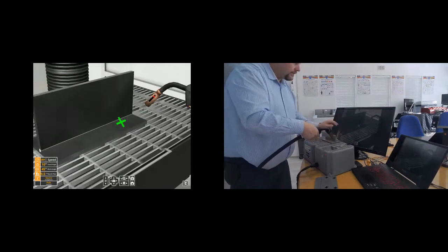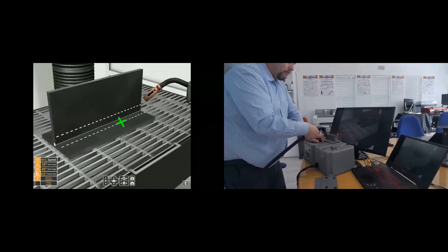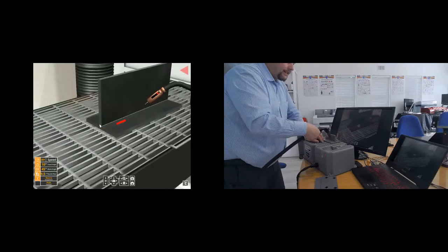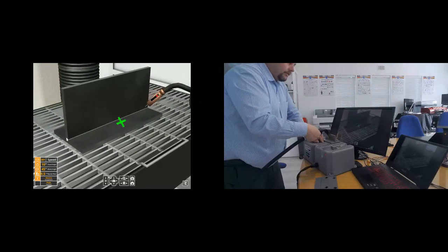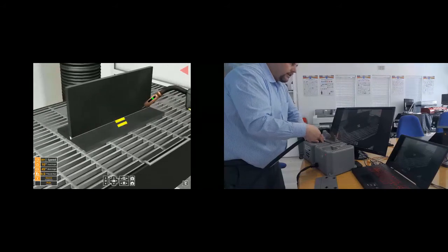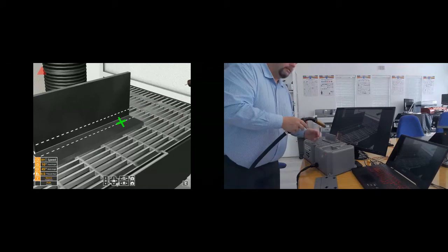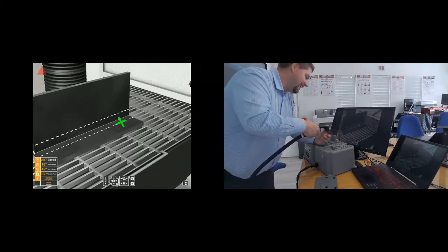And it's got a plus sign over there. So generally what that means is I need to speed up my welding. And if I've got a negative over there, it's telling me to go slower. Right? So let's quickly try and do this well. By the way, I'm not an expert welder.